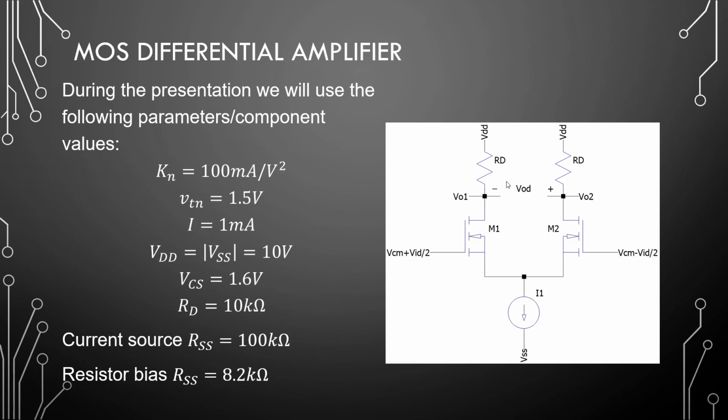Okay, differential also means that we look at these two outputs and the load will be sitting here in between, and we subtract the one output from the other. So typically Vout2 minus Vout1. The DC will cancel and the signal will be sitting in the middle right here. If we talk about single-ended mode, it is just taking one output of the circuit and not the fully differential output.